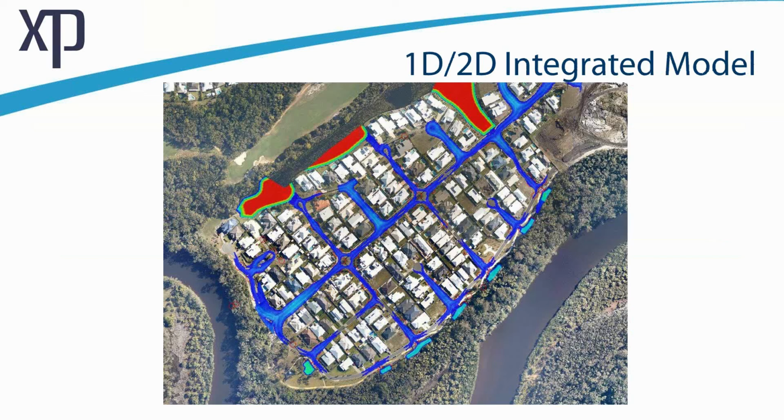And once we've paired that series of information together in a broad sense, we can then start to derive integrated 1D, 2D models where we can pair both data sets together. And as an output, we would expect to see inundation plots which tell us information about depths across the development area, as this is a particular example. This particular example wasn't interested in the dynamics of the creek system that surrounded this particular area. However, this model could be extended, of course, to take that information hydraulically into account, although boundary conditions were considered.